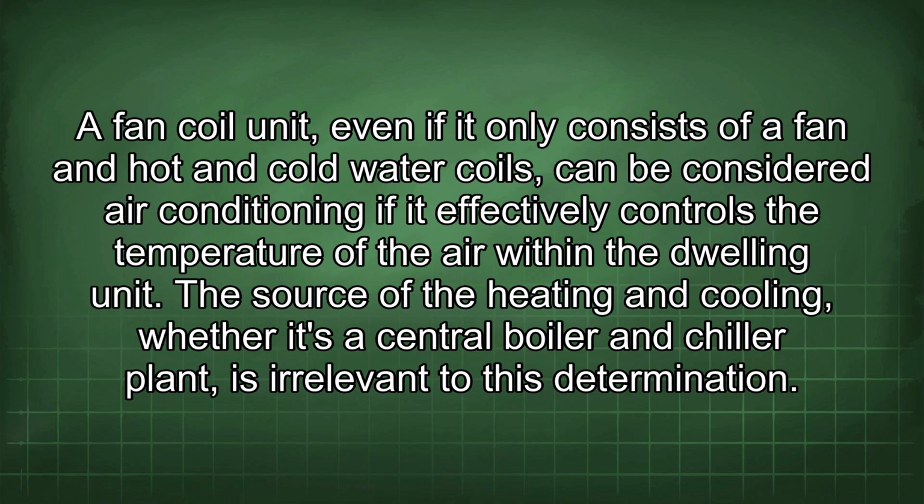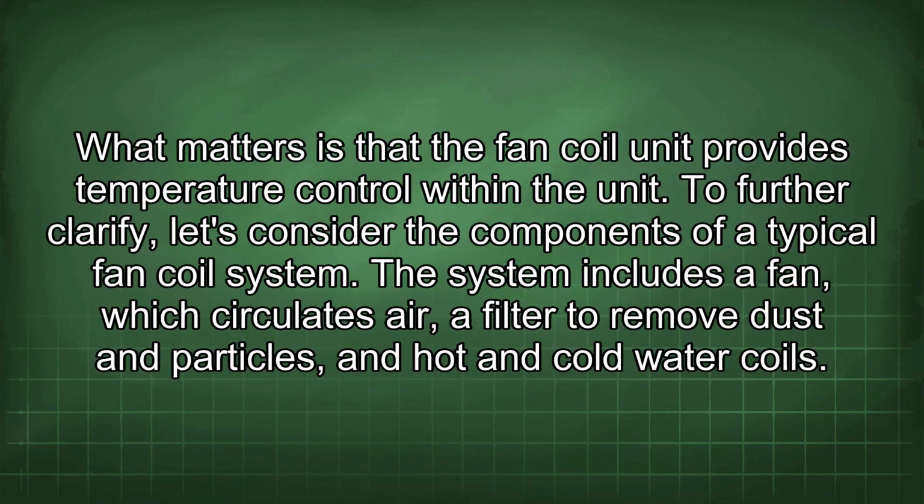A fan coil unit, even if it only consists of a fan and hot and cold water coils, can be considered air conditioning if it effectively controls the temperature of the air within the dwelling unit. The source of the heating and cooling, whether it's a central boiler and chiller plant, is irrelevant to this determination. What matters is that the fan coil unit provides temperature control within the unit.